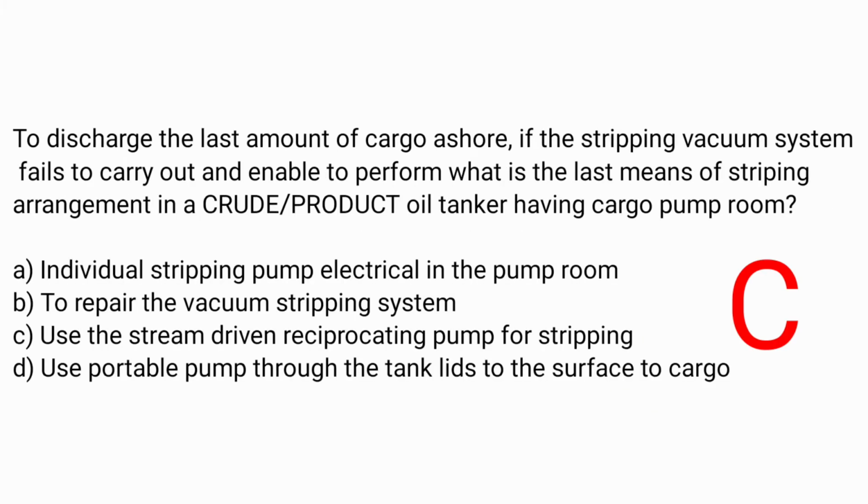To discharge the last amount of cargo ashore, if the stripping vacuum system fails and is unable to perform, what is the last means of stripping arrangement in a crude or product oil tanker having a cargo pump room? Answer C, use the steam-driven reciprocating pump for stripping.